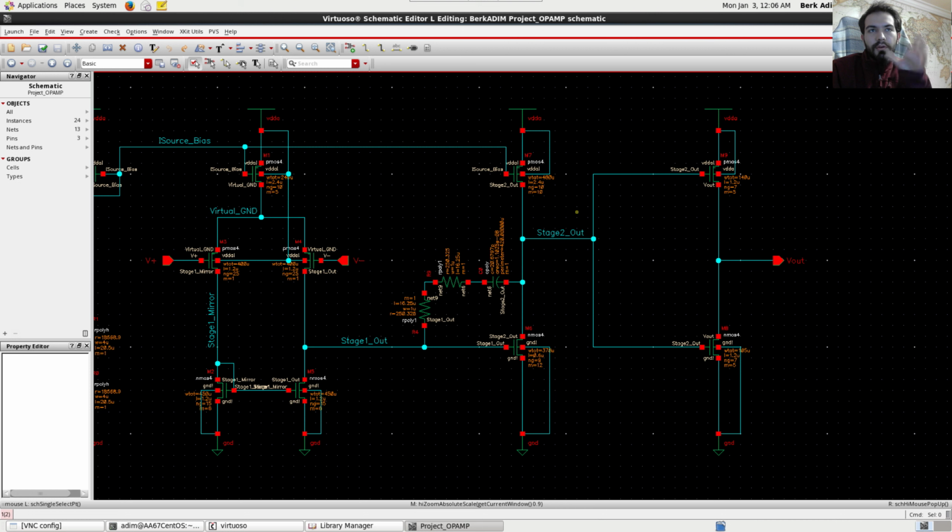So that was the inverted PSRR, by the way. It is not the effect of supply at the output, but the effect of output at the supply, let's say, the inverted one, so the values come up nice and positive. I am careful at clarifying this because you will see the uninverted version quite soon, because the standards can change between reports. But anyway, you will see it.